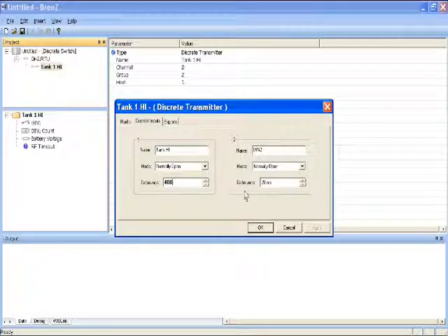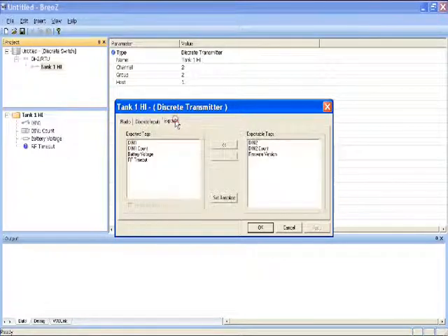Notice that there are two different points, so you can set up two different discrete inputs. Our device comes hardwired for two different switch capability, and you can hardwire any type of dry contact switch into said transmitter.